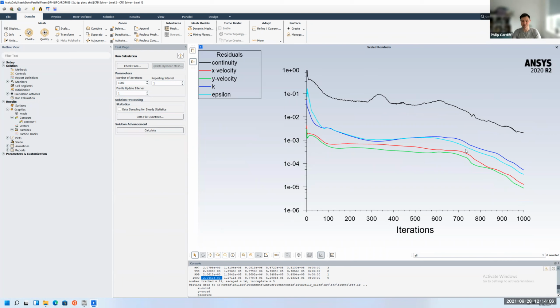But you can see in this case, it was much less efficient to use the simple solver than the coupled solver. The answer, assuming we're hitting the same tolerance, should be approximately the same if that tolerance is tight enough. And one other thing to note is the simple algorithm will use much less RAM than the coupled one. That may be a concern. I'm not monitoring my RAM here because it's not so big a case, but if it was a bigger case, the coupled solver tends to use much more RAM. It could be a factor of 5, for example.